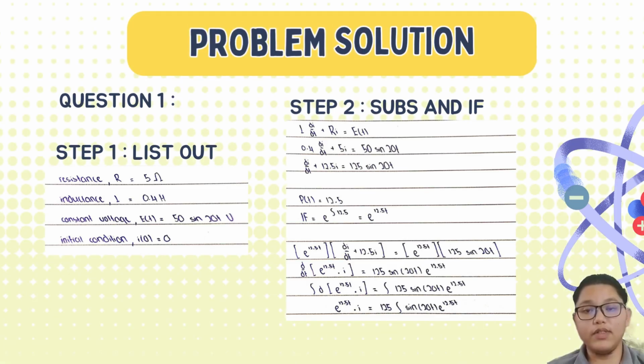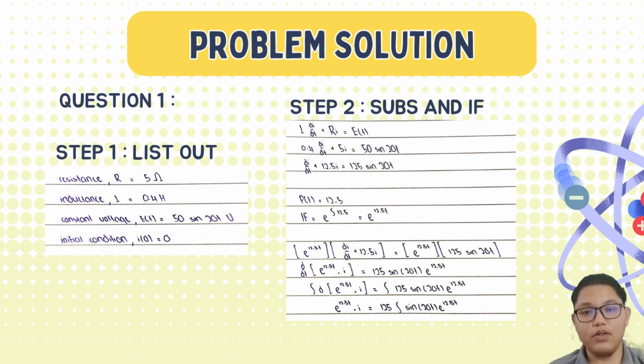For the first step to solve the equation, we list out all the information that we have been given. After that, the second step is to substitute the information given into the RL circuit formula. Hence, we will get 0.4 dI/dt plus 5I equals 50 sin 20t. To solve this equation, first we need to transform it into standard form, which gives dI/dt plus 12.5I equals 125 sin 20t.